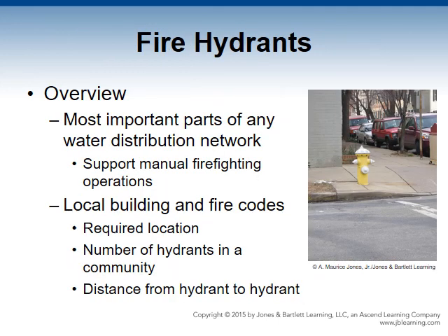The fire hydrant is one of the most important parts of any water distribution network. It supports manual firefighting operations by providing a point of connectivity to the water supply. To connect fire hoses to the hose nozzle on the fire hydrant, the caps on the hydrant must be removed with a hydrant wrench. Water flows from the hydrant onto the fire apparatus pumper. The operator determines pressure, flow, and requirements and uses a pump to supply the water to the fire hose lines or the FDC that is feeding the fire protection systems.